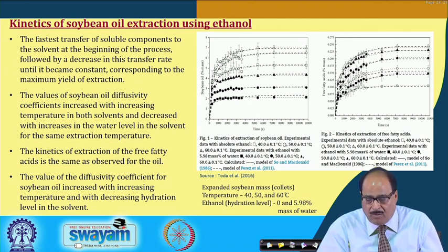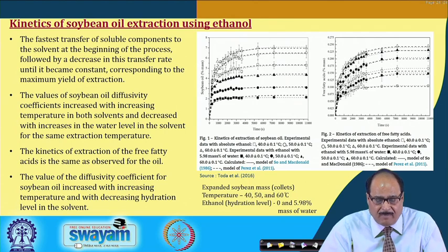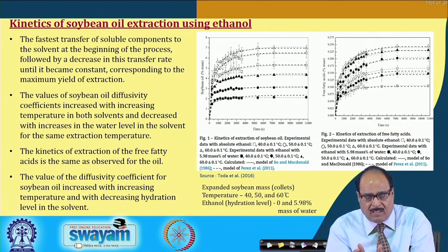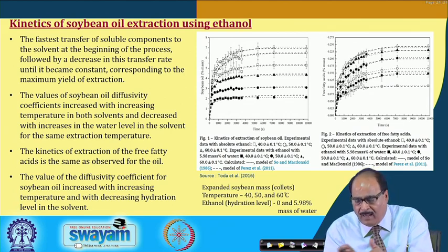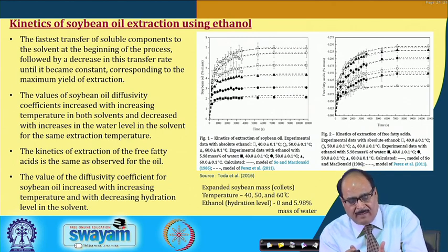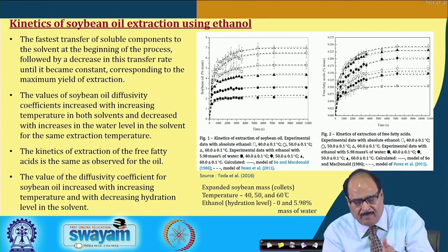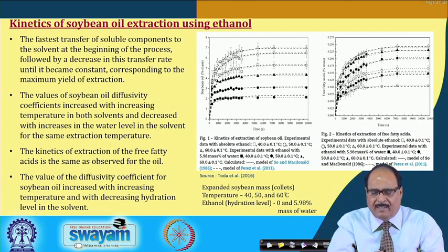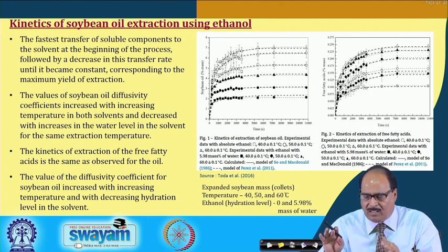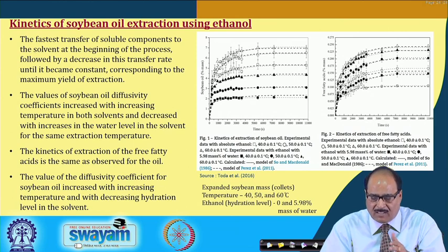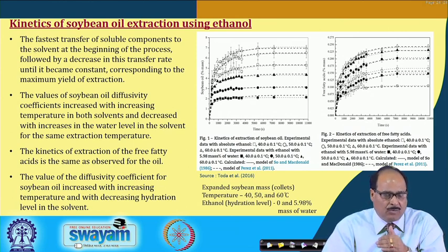or the kinetics of the extraction of whole soybean oil, okay. It increases up to a certain level, both the soybean oil as well as the free fatty acids. It increases initially at a very fast rate, then its rate of extraction becomes a little bit slow, and then finally it gets stabilized and becomes constant, depending, of course, upon the material conditions, process conditions, temperature, pressures and so on.